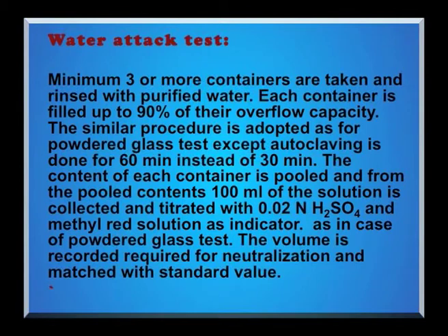The content of each container is pooled, and from the pooled contents 100 ml of the solution is collected and titrated with 0.02 normal H2SO4 and methyl red solution as an indicator. As in the case of the powdered glass test we discussed earlier, the volume required for neutralization is matched with the standard value. Now we'll move towards another container, that is the plastic container.